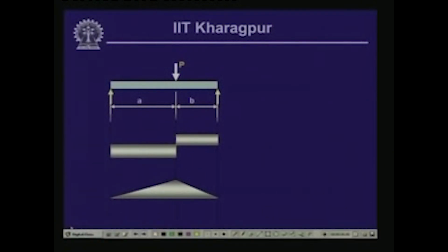You see, this is the shear force and the bending moment diagram of this particular beam, which is loaded with the concentrated load P over the span L, over the length of the beam as L. If we have a concentrated load which is placed at a distance of A, we have the shear force variation. Now, as we have seen, the shear force here is, I am sorry, this is negative over here, this is negative and this is positive. Now, the bending moment, as we have seen, is positive for the whole region.